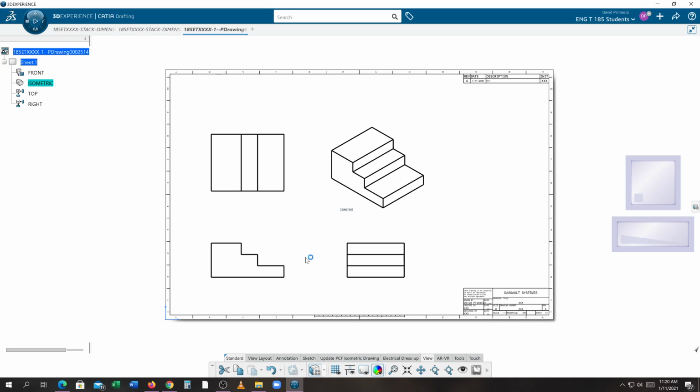And that's how you lay out your views using the wizard command. Again, that is found in the layout tab. Hit the arrow to go to the right. That's the only thing, is they like to hide stuff on us. Go to the view wizard and you can create those same 4 views in no time.